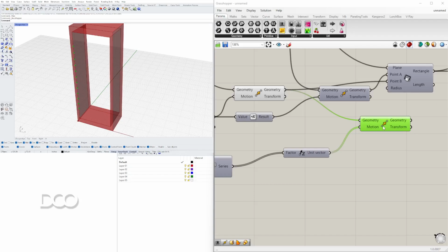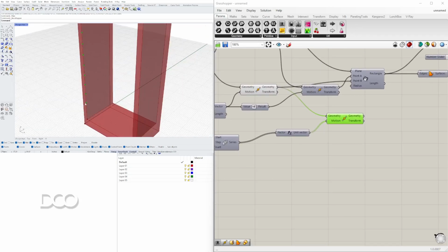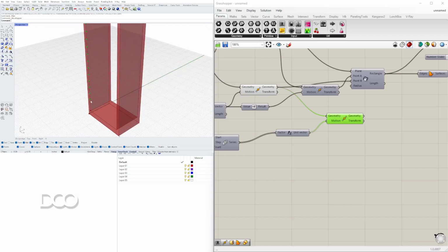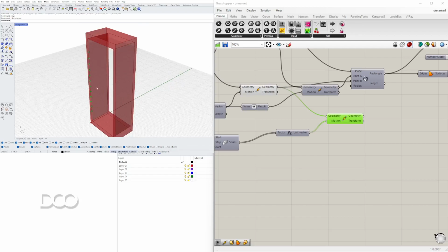So at this point, what we'll do is take this and we're going to move it to the inside. Now, which way is it going to be? Well, it's going to be positive Y. And what is important to notice is that we're actually only going to do one side, because then it's symmetrical, so we can use a mirror command and it'll mirror it to each side.